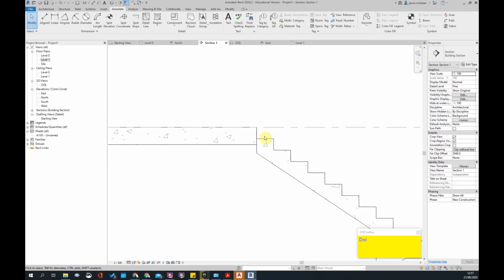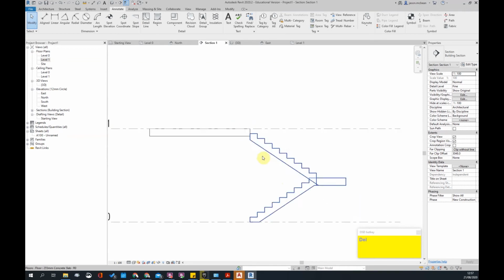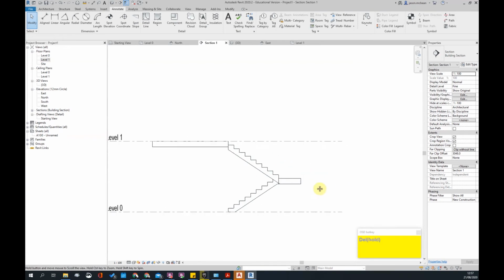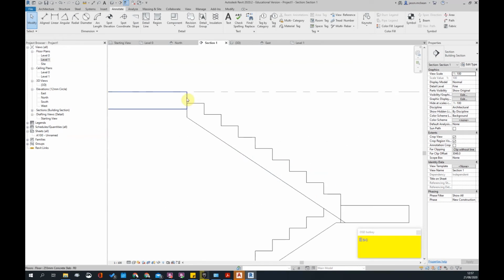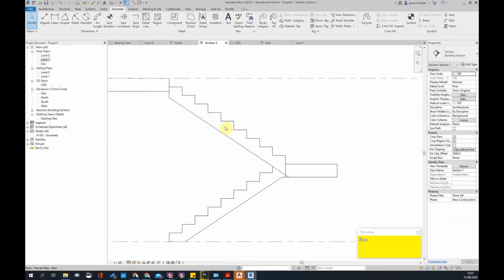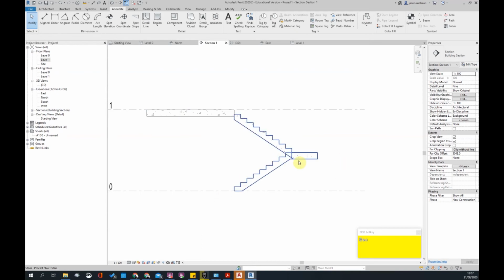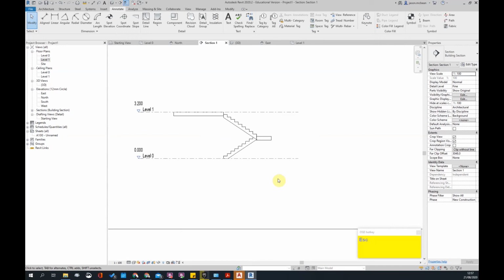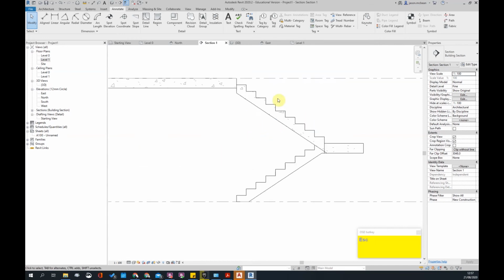But generally this is how it will stop, because then this is where your slab starts, and you usually get a beam underneath here. So that's that in a nutshell. Sometimes they'll cast a precast stair will go into here, and that's when you'll have that little nudge. But generally, in South Africa, they cast it all as an in situ casted stair, so it'll read that way. It will be modeled like that, but that's fine.